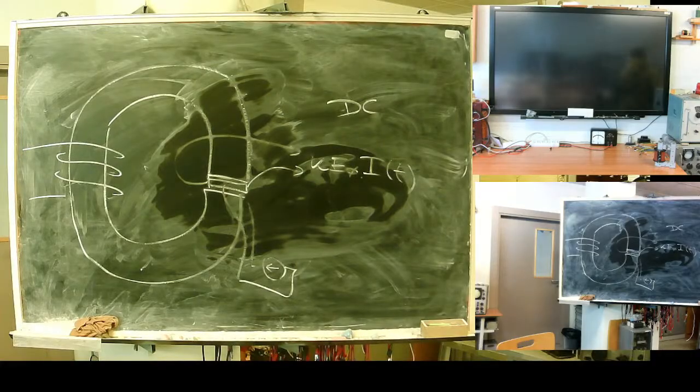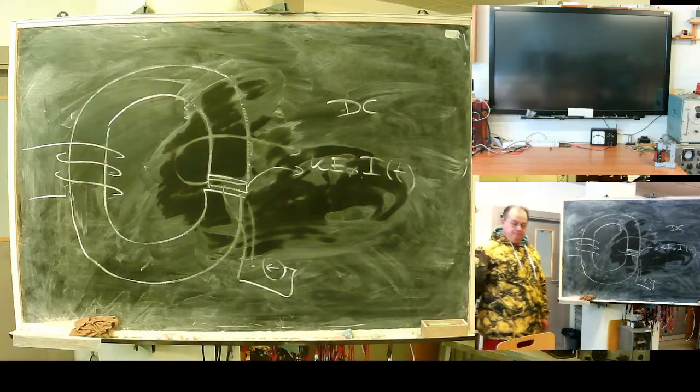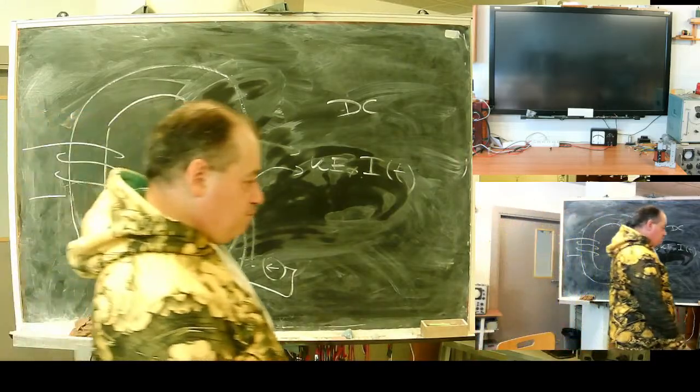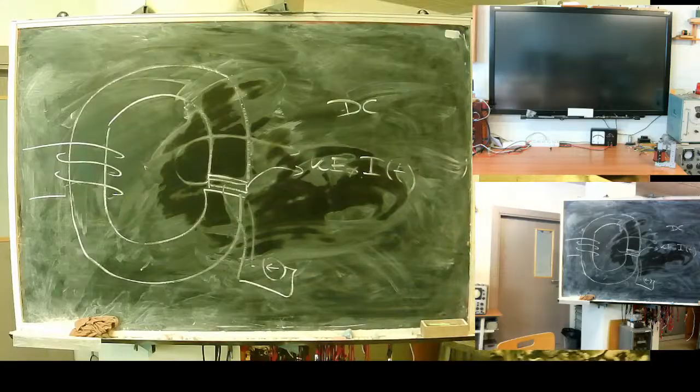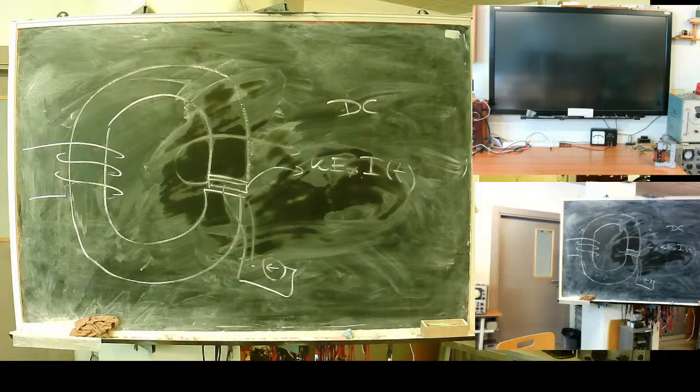Such a design fails because a Hall sensor has quite a limited range of precise operation. And second problem, zero drift. The zero point drifts mostly under the influence of outer temperature. This is garbage, it works for nothing.